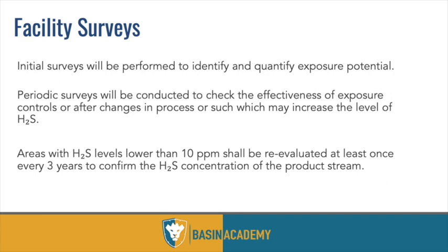So, they should be testing these wells at least every year, every 3 years, depending on their plan, and then communicating that to subcontractors. Anything over 10 parts should have a breathing air system on there. If you see a sign that says danger or warning, H2S may be present, that's essentially true because H2S can be everywhere. Some companies like to put these on every well, all right? So keep that in mind.